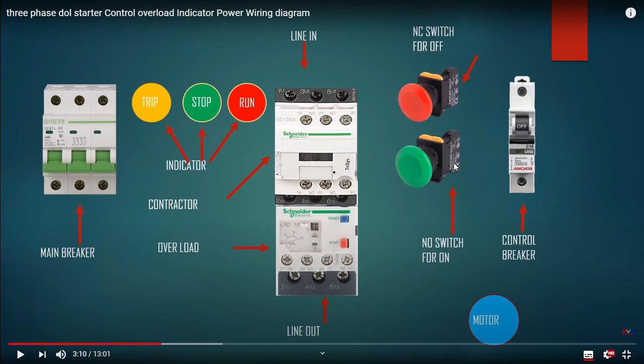When we press the green push button, it will signal the running light, and when we press this, it will signal stop. Then when the overload trips, the yellow pilot light will light.